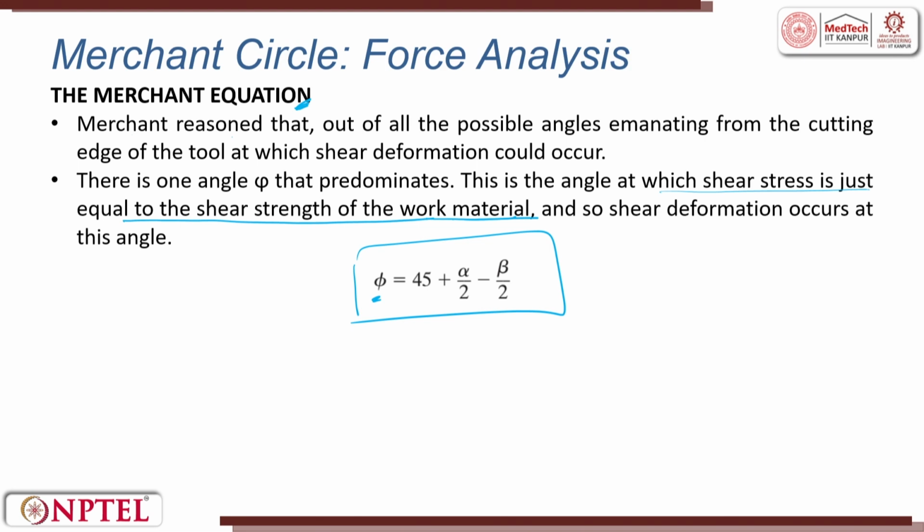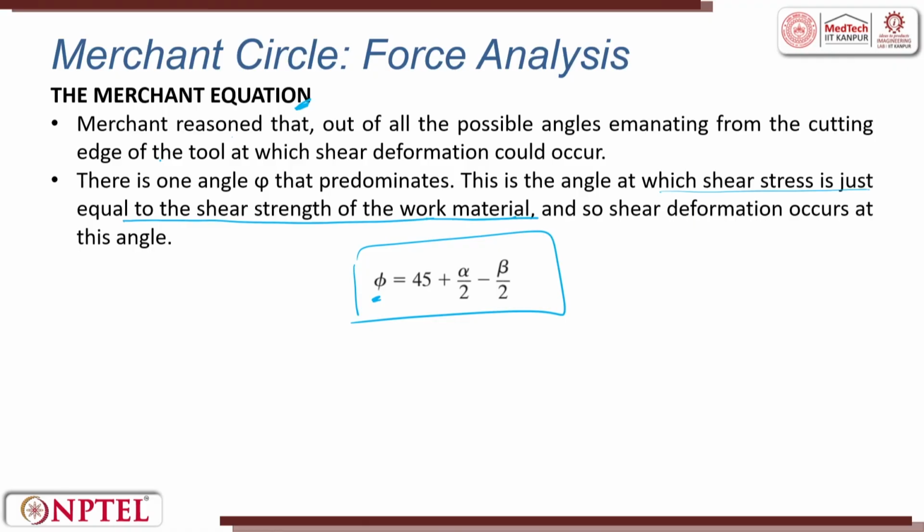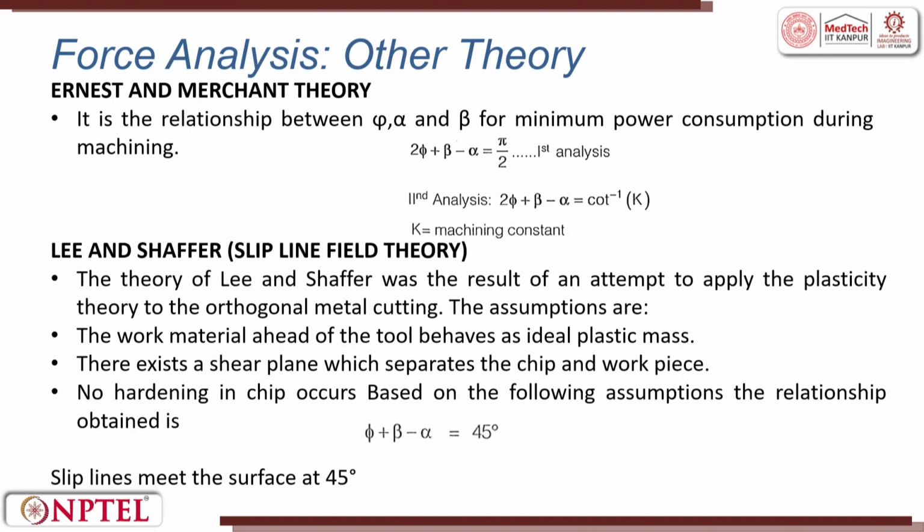Here it is very close to oblique. It has quite a lot of approximations, and by and large by using first principles, you can try to have a rough approximation of the forces. So, that is why the Merchant circle equation and Merchant circle diagram are very important while teaching metal cutting.